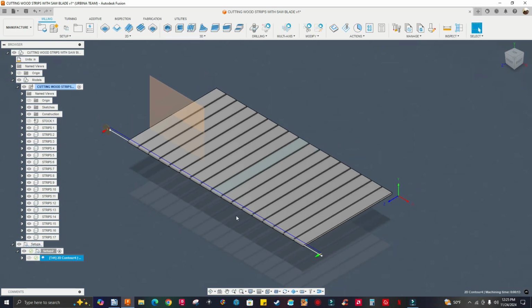Now, how do I bring this toolpath over here? You can go back to the design workspace and draw another line here, or you can just mirror this line as well in the 2D sketch environment. You can mirror that using a construction line right in the middle. You can. But the fastest, easiest way for me is to just pattern this toolpath.